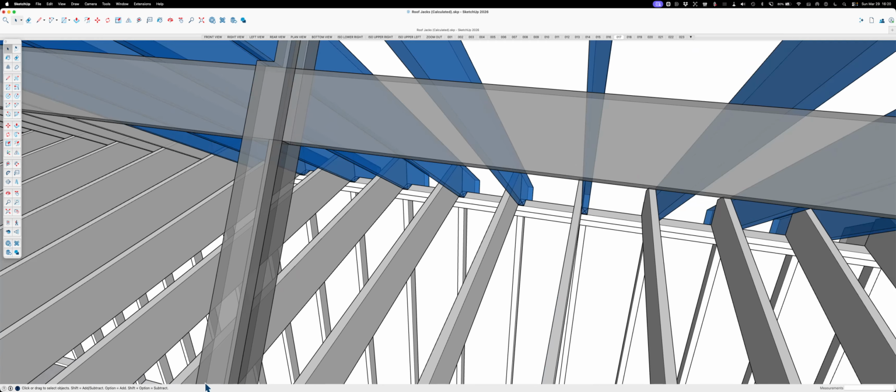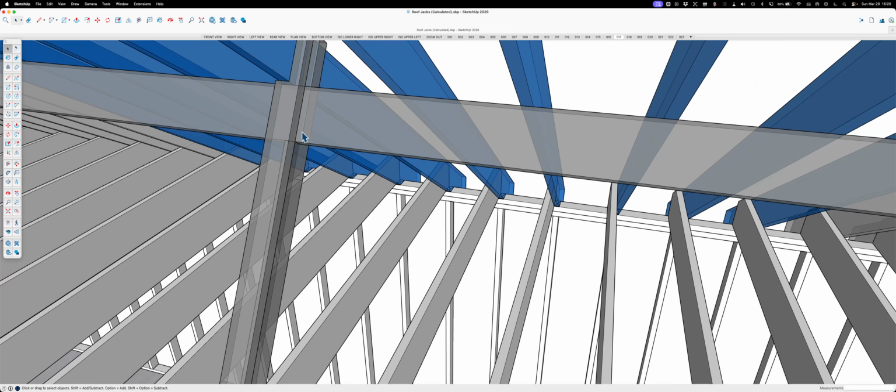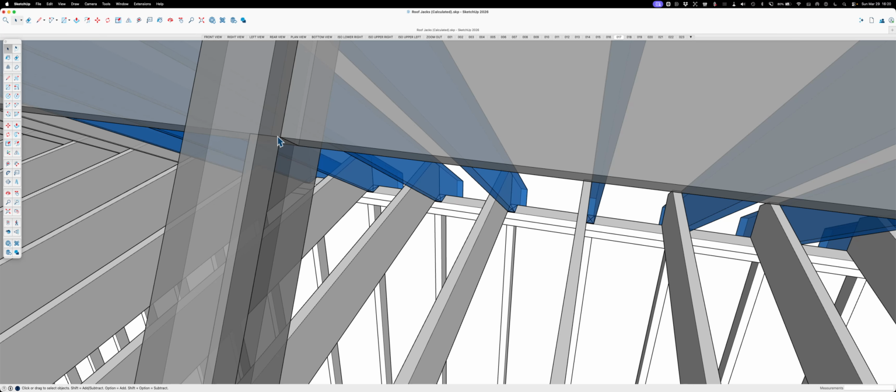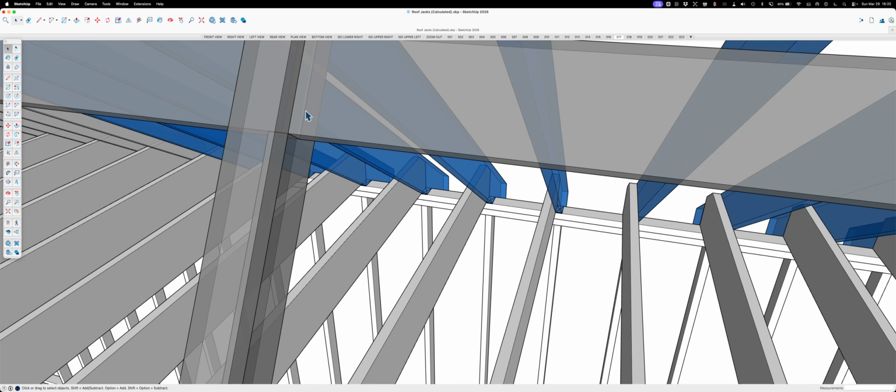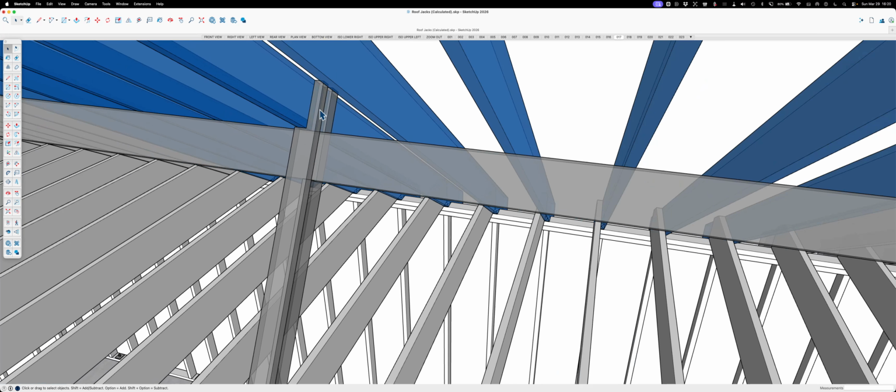You get a quick measurement, and you measure to the bottom, and whatever that is, then you also measure all the way up to the top of the rafter. And as you can see right here, I would notch out 1.5 inches by the whole length. And then when I go to put this in, I slide it over to where it's touching a rafter, and I beat the bottom nice and snug. Careful not to put a crown in this thing. And then I can shoot through the purlin, a couple nails into the back of this, and then a couple nails sideways into this rafter, and then 2 or 3 nails down into the wall.